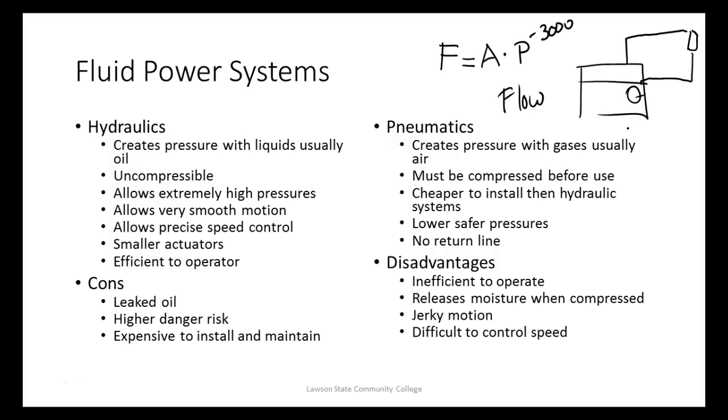But to create pressure, gases must be compressed before we use them. Gases are very compressible, right? You understand that? So we have to compress it before we use it. It's cheaper to install than hydraulic systems. It's safer because the pressures are lower. We can't have extremely high pressures, because what happens when we pressurize gases? They turn into liquids. So we can't run them at extremely high pressure because they would turn into very cold liquids too.